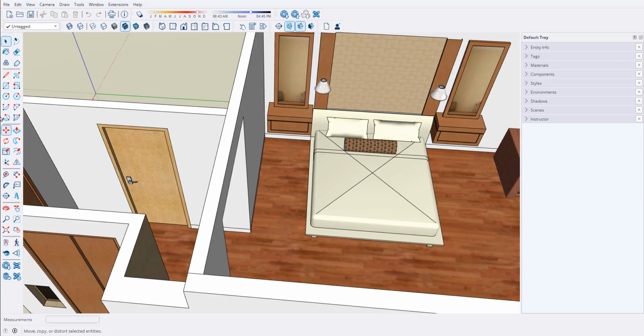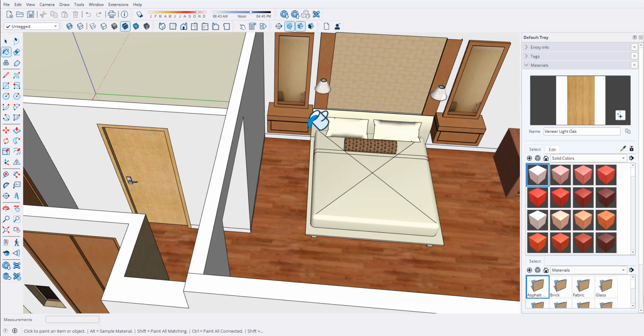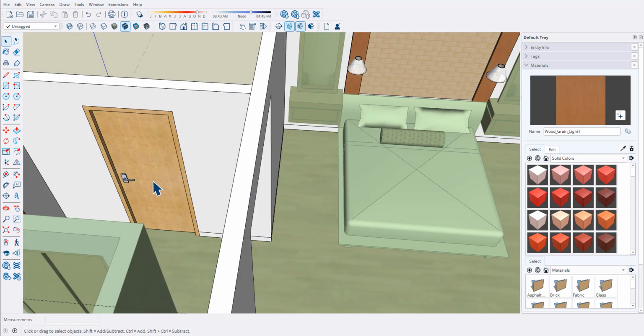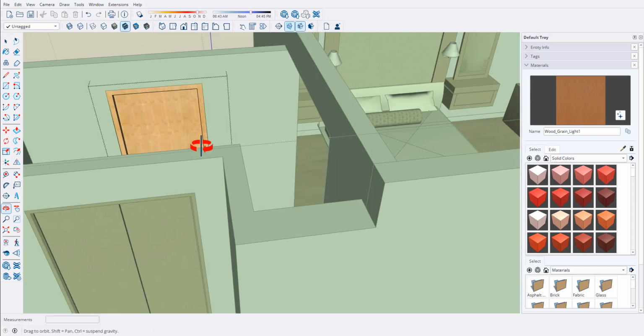I'm going to go ahead and go to Paint Bucket Tool, so B for Paint Bucket Tool. And what I want to do is select, let's say, this material. This is the color we're looking for all our wood products. So I'm going to hold down the Alt key, click here, and then go to the door, use the space bar, click to the door, click inside it. So now I'm inside the door component.